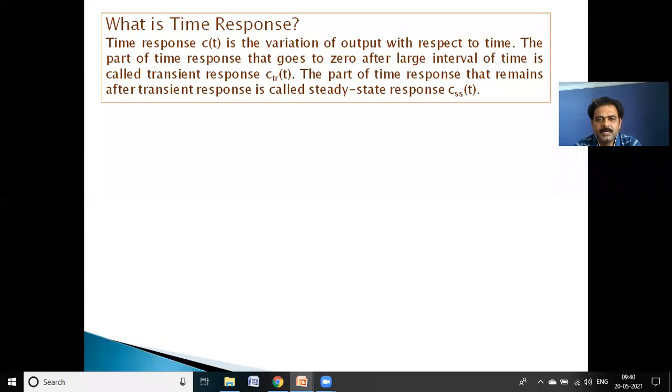But because of the capacitance and inductance, the energy storing elements present inside the circuit, it takes a certain time to reach 230 volts. Before it reaches 230 volts, it reaches a maximum of 400 volts or more in some cases, maybe 1000 volts. And finally, after a certain time, it reaches 230 volts.